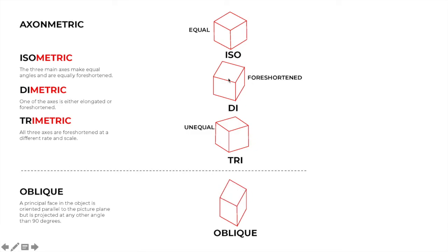Look back at the isometric, dimetric and trimetric: you can see the top plane of this cube has been foreshortened. But in this oblique view, that top view of the cube remains true. It is still a square. It's just been rotated, probably to line up with a 30, 60, 90 triangle. That looks about 30 degrees there, and about 60 degrees there to the parallel. And so by simply turning that square and projecting these lines down, we have an oblique view of that particular cube.